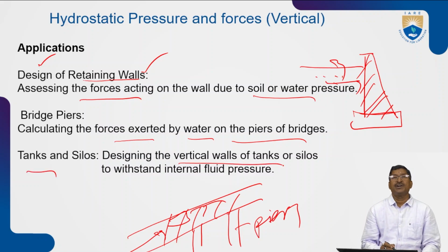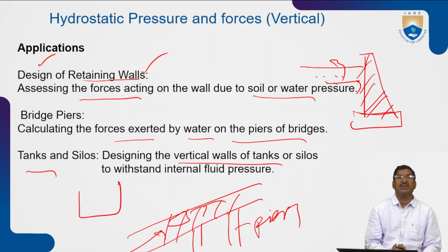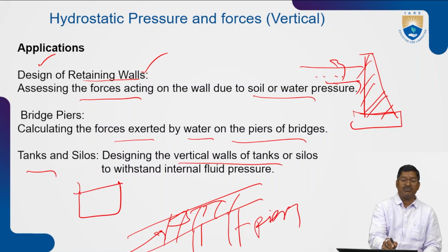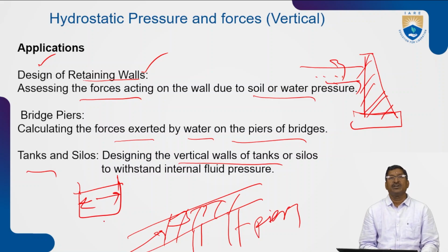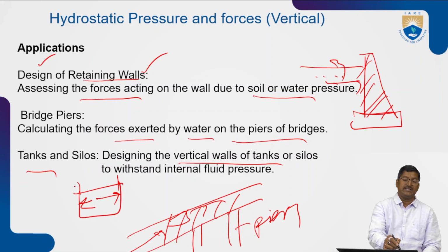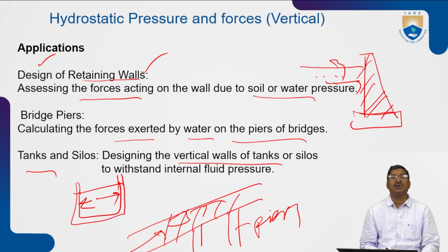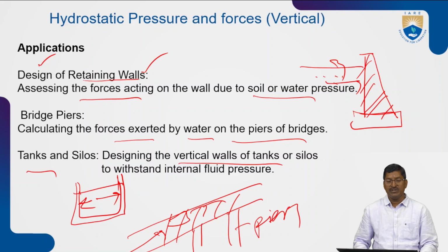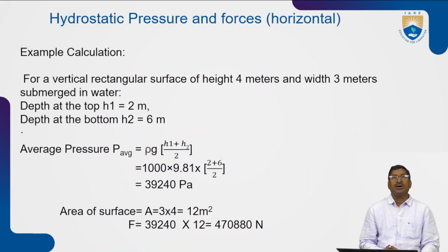These also underground tanks are there, overhead tanks are there. So a tank also has a wall surface. If water is inside, then the water force will act towards the outside. Based on the fluid pressure, we have to design the wall thickness and base thickness of the tanks. So these are the applications of hydrostatic forces.